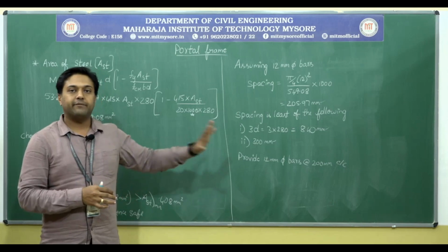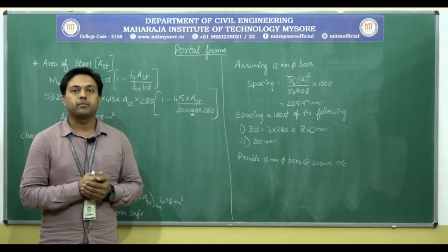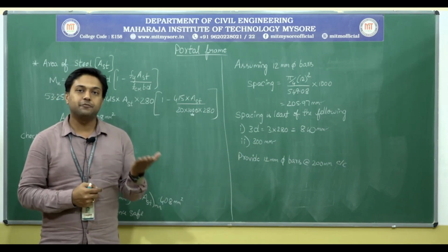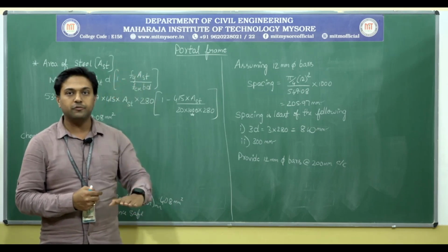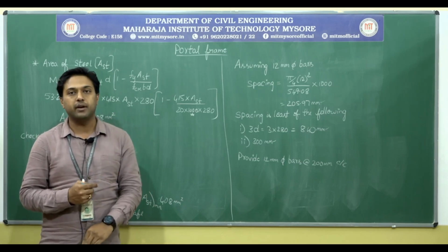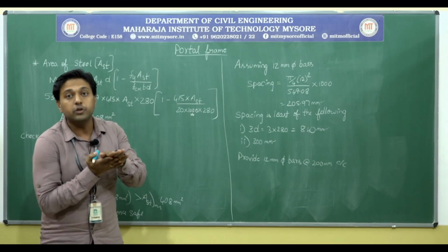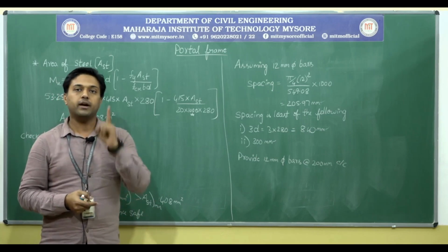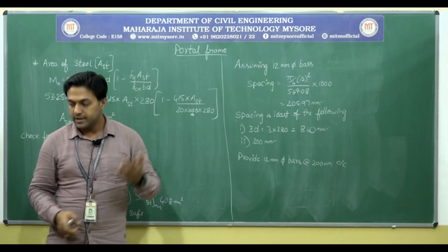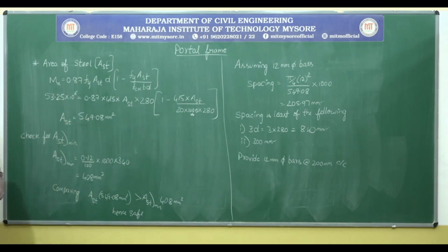Okay, so we have calculated the spacing. The next thing is, as the footing is resting on the soil, whenever the load is transferred from the column to the footing and from the footing to the surrounding soil, the footing will be subjected to huge shear with the soil. So that's why I need to do the check for shear. Okay, so let me rub all these things.